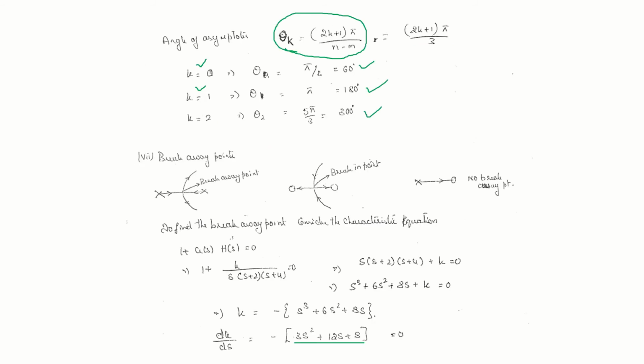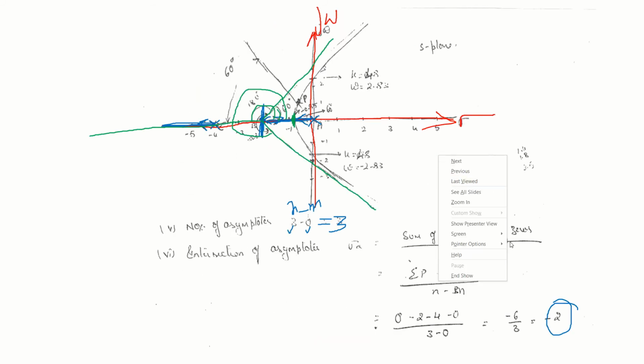Next thing is, you see here, now I'll draw the root locus. So this root locus is coming from here, this is coming from here, they break. Now these asymptotes help us to go in what direction the root locus should be drawn. So root locus is drawn in such a way, every point should make an angle of 180 degree and the open loop magnitude should be 1.